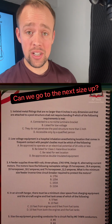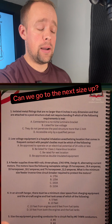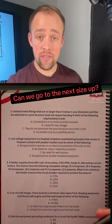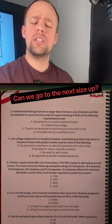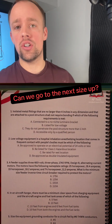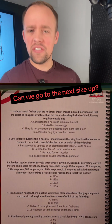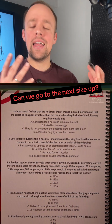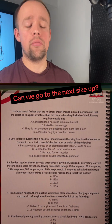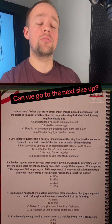Okay, first off, I'm not actually going to answer this question, but I am going to address the DM that I received. So I got a final answer, and this gentleman said, hold on, your answer is incorrect because you didn't round up. For certain motor applications, it could be sizing the branch circuit overcurrent protective device, you will often see if the calculated ampacity does not correspond to a standard ampere rating for an overcurrent protective device, you can go to the next size up in accordance with Table 240.6.